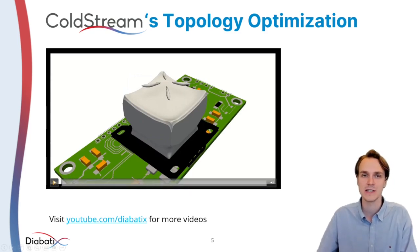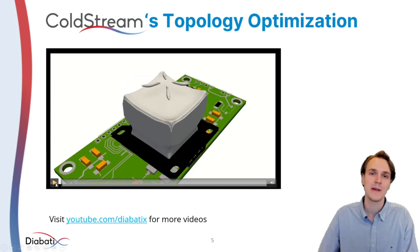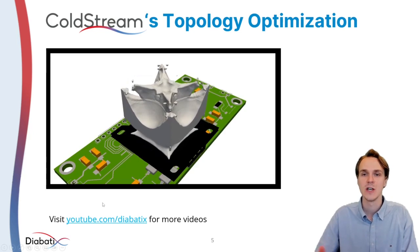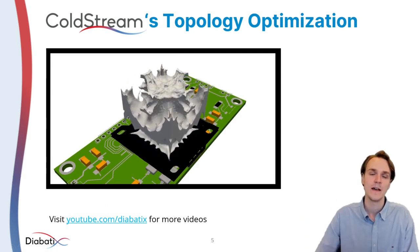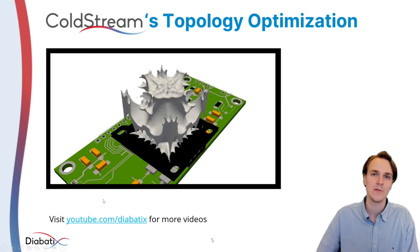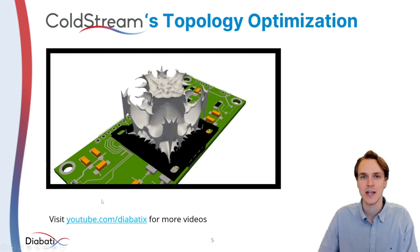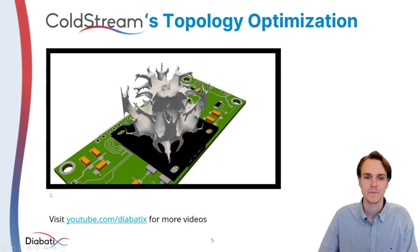But the principle is the same: if you specify a certain design volume, telling our optimizer this is where you have the freedom to perform the topology optimization, what will happen is ColdStream will cycle through hundreds of different designs, going quite fast here in the video, each single step of the way with a full CFD simulation to check how the performance is as we're approaching a thermal optimum.